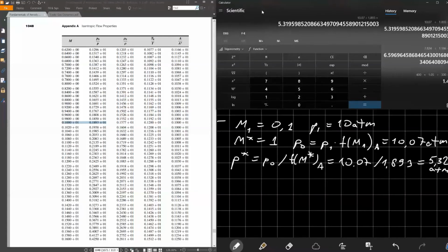Do not forget that by receiving two properties of a compressible flow, you can obtain as the result also two properties of the compressible flow. You cannot obtain more than two properties. And by setting three properties of the compressible flow, like one kinetic and two thermodynamic, you can obtain any quantities, any parameters you can have in the compressible flow. So that's the trick.